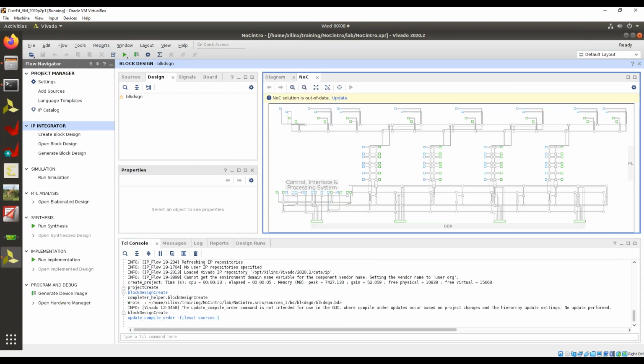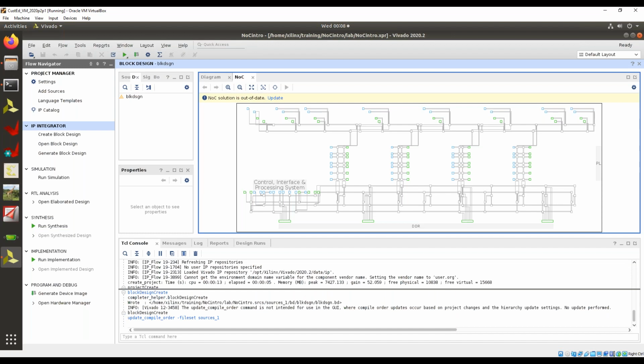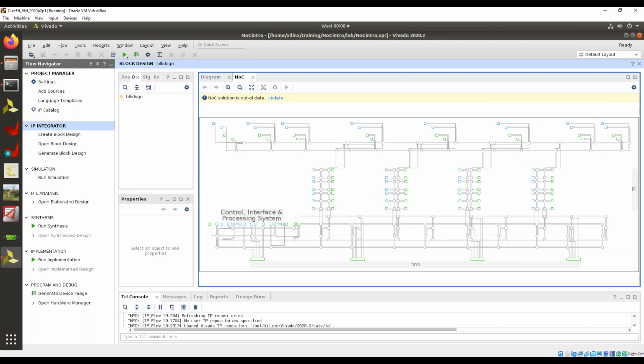look at that, it's got a picture of the NoC on that. So this is an empty NoC. This is what the hardware actually looks like. We talked about this being mapped to the silicon. Yes, it's a high level look at it. It is obviously not perfect in the way that it shows it, but for the most part, you go in and you can see, okay, at the top level of this, this is our horizontal 2 paths. This is our horizontal 4 paths that work its way through, and then our vertical 2, 2, 2, and 2.